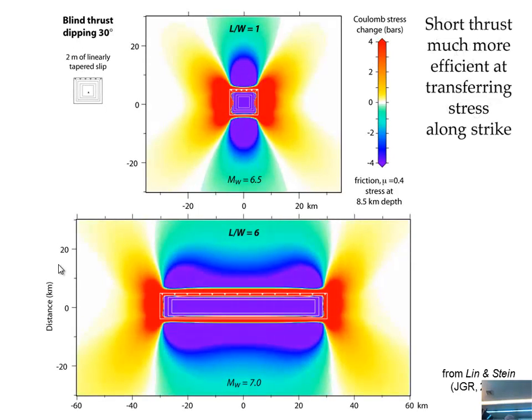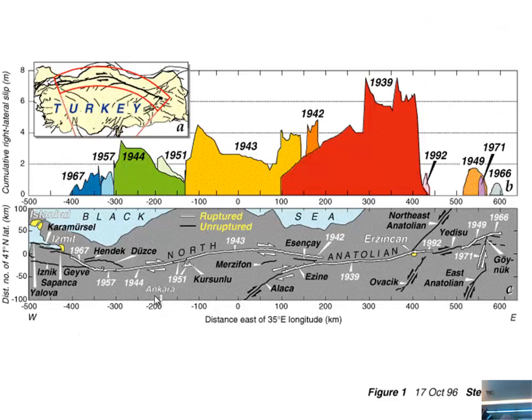And this is changing aspect ratio. So what this shows is really the location to have enhanced aftershocks or possibility of triggered bigger earthquakes is on the end of an existing fault. So if you break this fault, it's most likely going to want to cause failure basically along that same fault for long strike. So let me keep going.